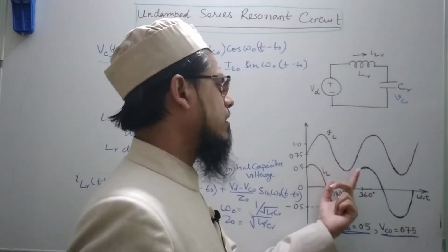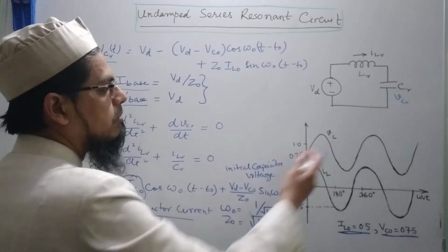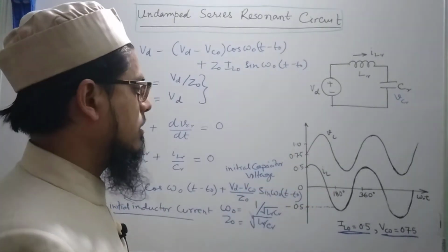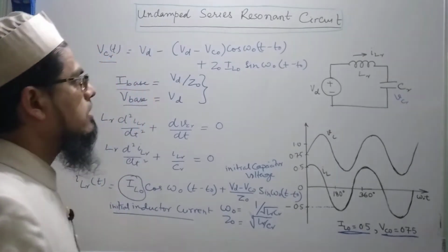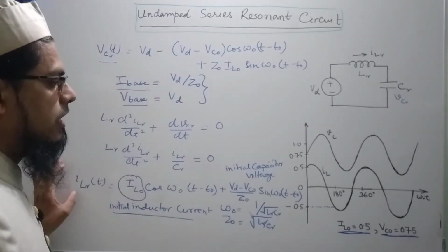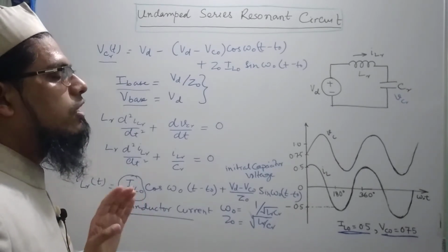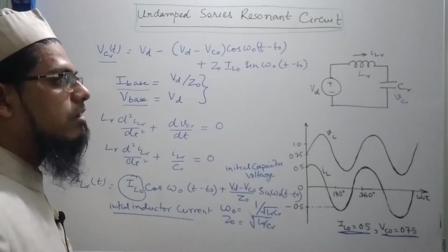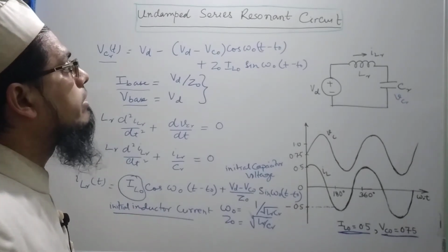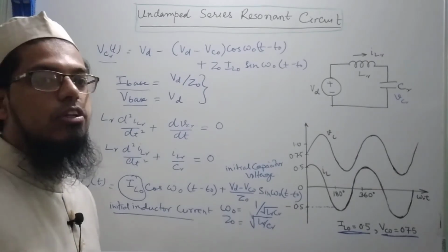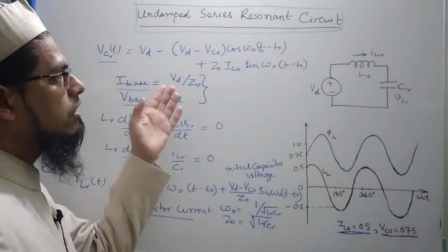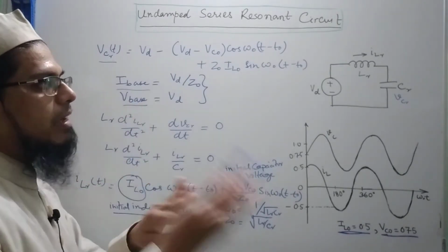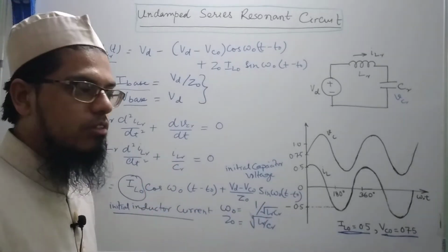So you can see a clear phase lag between the voltage appearing across the capacitor and the current flowing in the inductor. These two expressions are quite important, and when we discuss series and parallel resonant load resonant converters, we would be invoking these two relations. For series we will be invoking these; for parallel I have to derive the relations again.